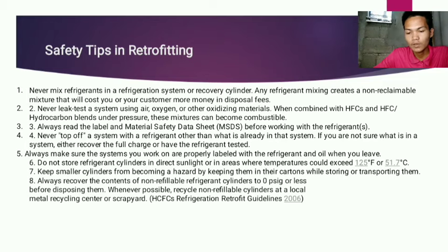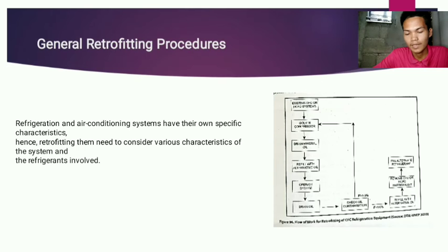Always recover the contents of non-refillable refrigerant cylinders to 0 PSIG or less before disposing of them. Whenever possible, recycle non-refillable cylinders at a local metal recycling center or scrapyard. Refrigeration and air conditioning systems have their own specific characteristics, hence retrofitting them needs to consider various characteristics of the system and the refrigerant involved.